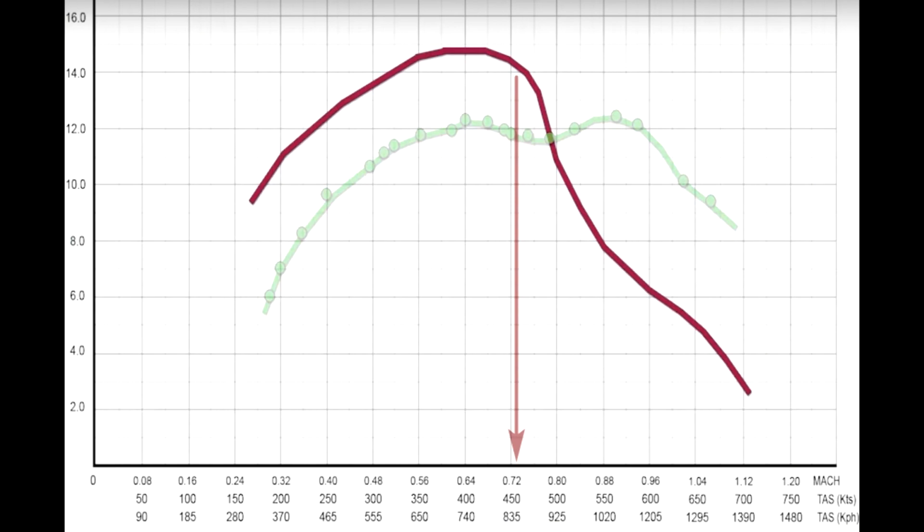Even more bizarrely, the slight flattening of the curve, a signature of the supersonic regime, appeared well before the aircraft had even reached transonic speed. And finally, if you extend the brown line down to the horizontal axis, where turn rate equals 0, in other words, where the aircraft can fly only straight and level, it bottoms out at a meager Mach 1.2.